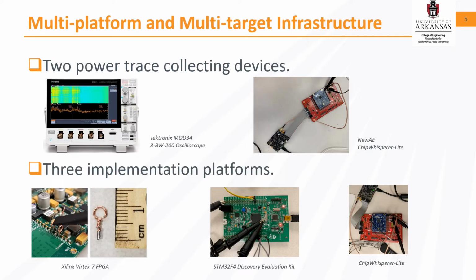At Arkansas, we have developed a multi-platform and multi-target infrastructure to perform power-based side channel attacks. We have a Tektronix oscilloscope and a ChipWhisperer Lite to collect power traces. We also have 3 implementation platforms, including one FPGA for hardware implementation and 2 microcontroller boards for software implementations.